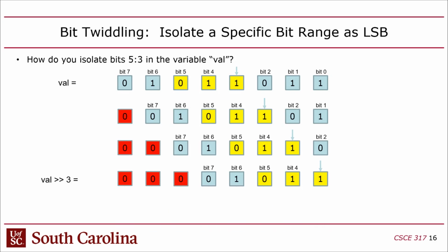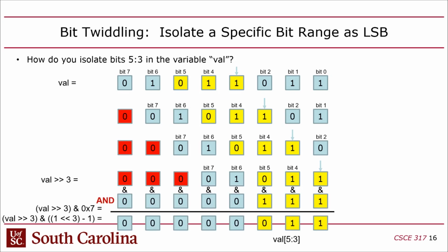now, obviously if I shift it, I'm going to have 3 zeros up here that are shifted in. But I still have garbage bits in between the bits I shifted in and the bits I want. I still have these 2 garbage bits, the 0 and 1, that I got to get rid of. So to get rid of those, I have to mask off. And this is where the multi-bit thing comes into it. So I need a temporary value.